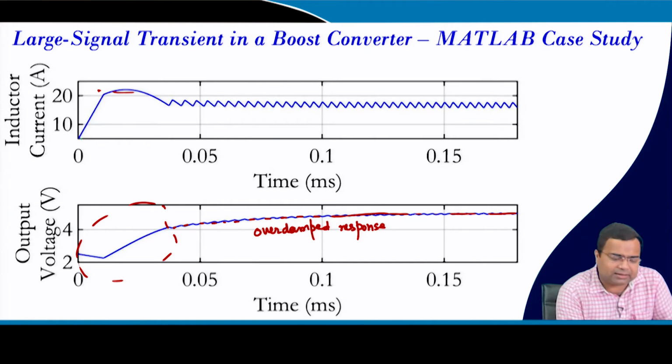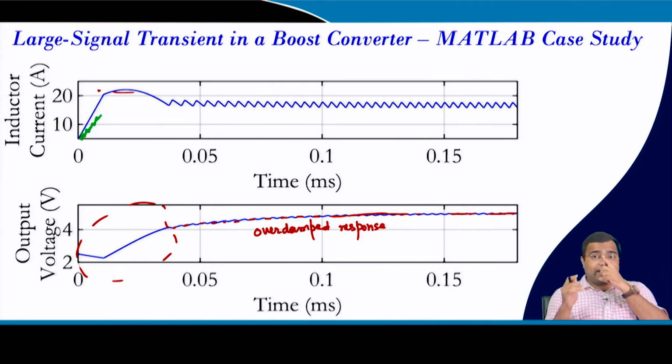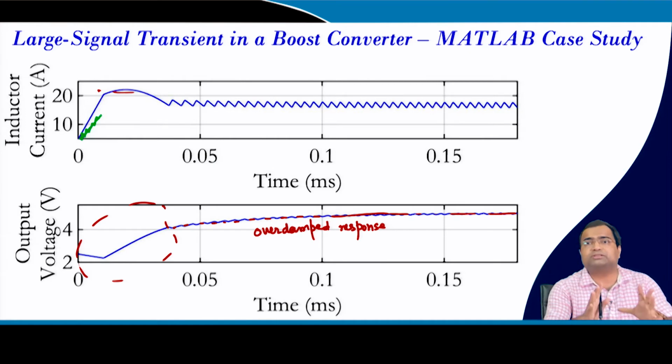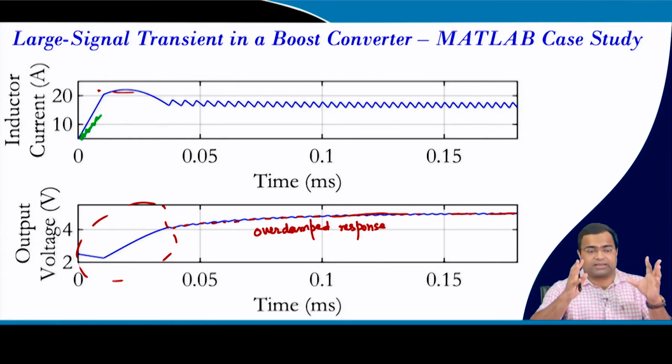But if you start raising the voltage slowly, because you may not get off operation because your voltage is starting from 0, so it will rise. So, you need to be very careful about the operation of the boost converter, right. Because initially the inductor voltage is high, but the output voltage is very low. So, you need to slowly rise, and you need to consider a special startup circuit. That is very important for a boost converter.